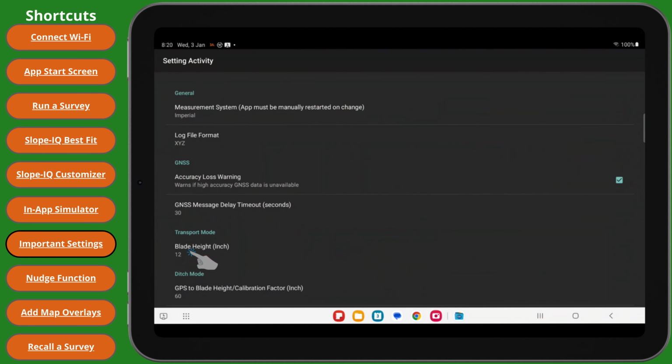The most critical setting to make sure you enter correctly is the transport mode blade height. This is the height of the blade or cutting edge above the ground when the implement is lifted in its field transport position. When you drive a survey, we assume the implement is in this position, and subtract this distance from the survey elevations to accurately calculate true ground elevation. Tap on the setting to change it.